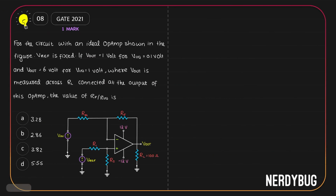Let us see the next problem. We have a circuit with an ideal OpAmp. V reference is fixed. When V input is 0.1 volt, V output is 1 volt. And when V input is 1 volt, V output is 6 volt. What we have to find out is the value of RF by Rin. It is also given that Vout is measured across RL that is connected at the output of the OpAmp, which is basic information.